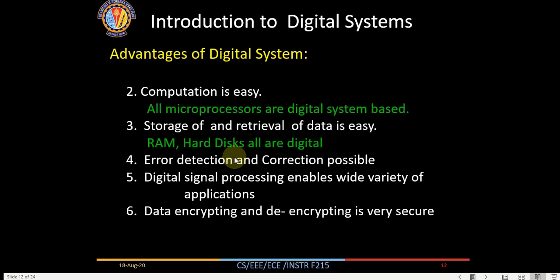Most of my voice signal will be from 1 kilohertz to 3 kilohertz. In that bandwidth will be the maximum voice content. So when I transmit my signal, along with my voice there is some power supply noise which is also transmitted. At the receiving end, in earlier days I used to have a high pass filter, an RC, resistance capacitance filter, which filters out this 50 hertz so that the noise is eliminated. So there are various ways you can do signal processing, and they were all done in hardware in the earlier days.